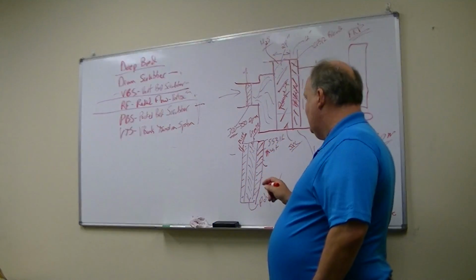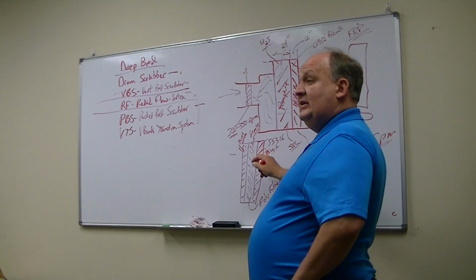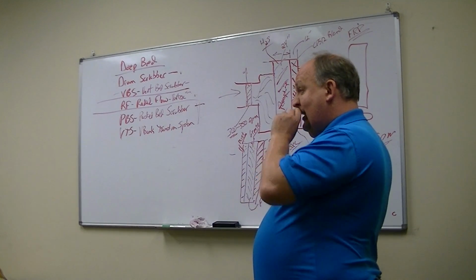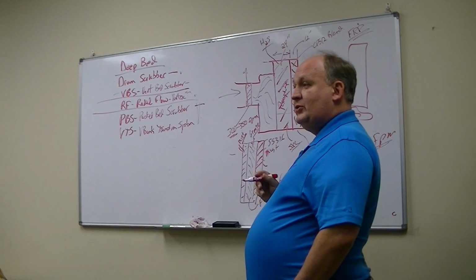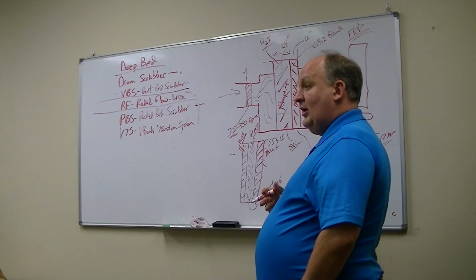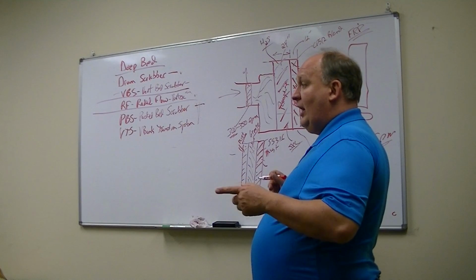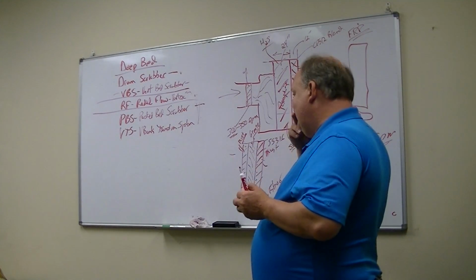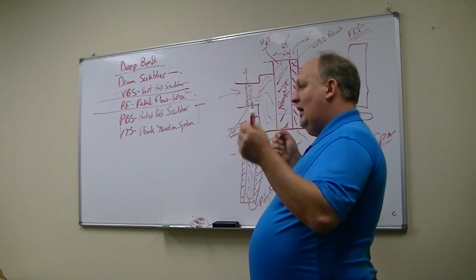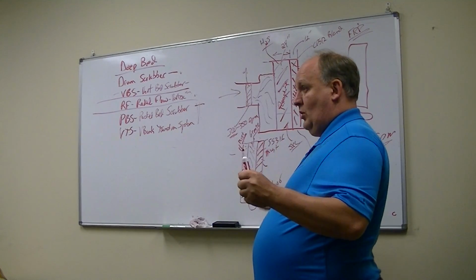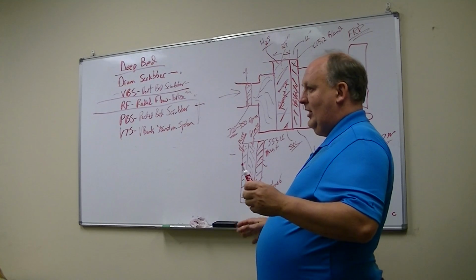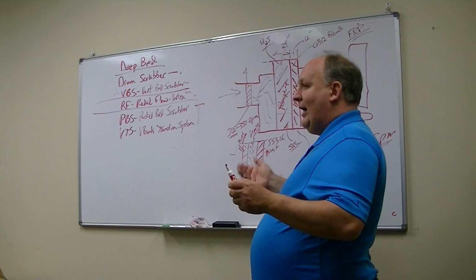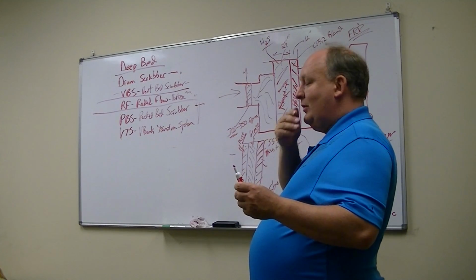Now I'll also mention to you, this thing is not easy to clean, to get the grease out of. These are super fine fibers in there, and when you guys go out for startup, you really need to talk to the customer, and we really need to update the O&M about how to clean this thing. And the way to clean this is, first you take the pad out, and the customer should always order a spare set of pads. We don't give them to them for free, but a lot of times in the project specs they'll order an extra pad, or after the project they'll ask for an extra pad.